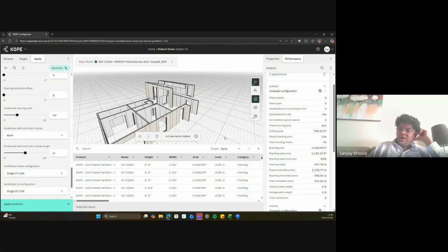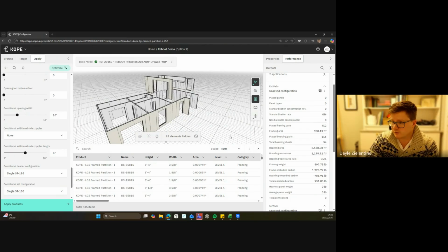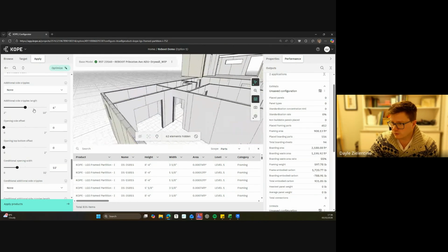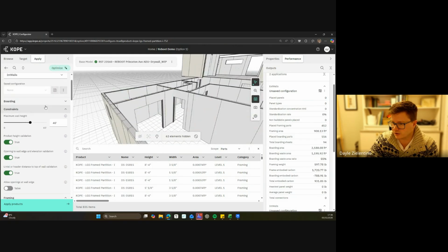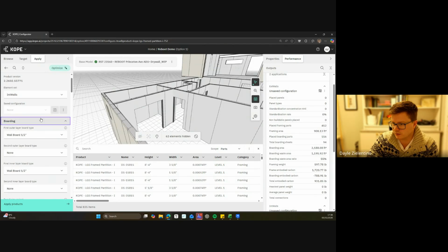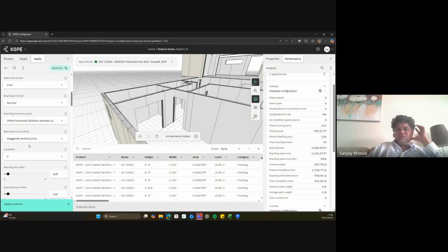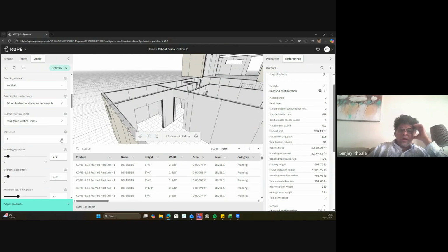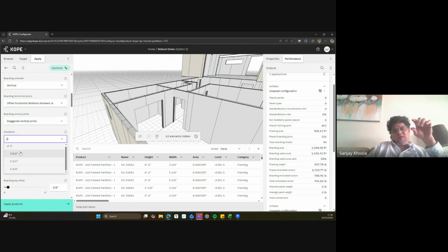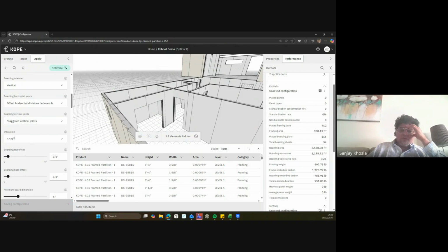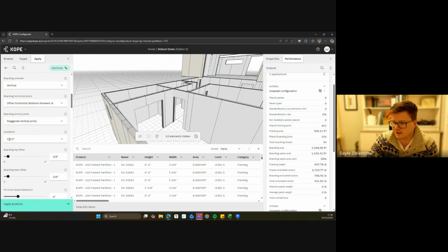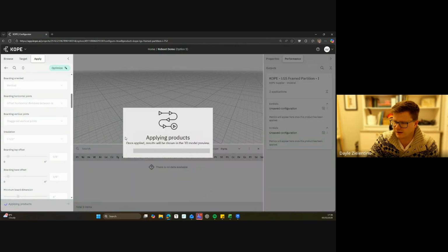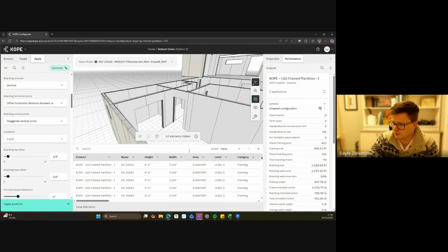But what about insulation and cladding? Oh, that's within there as well. That's already in here. It was just that when I applied this, I didn't have any insulation inside the walls. But if I go back to boarding and say, can you apply a certain logic, just as a template, and show what sort of insulation would be needed so that we can get to the cut list, if you will, to the specificity, the length, and all that stuff based on the wall panels? So if I do the insulation, I'm just going to add in 3.5 inches of insulation. Now, this might actually be a bit too big for these walls. But as an example, if I then group by